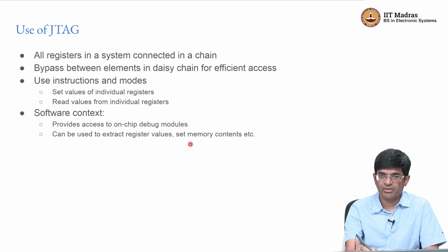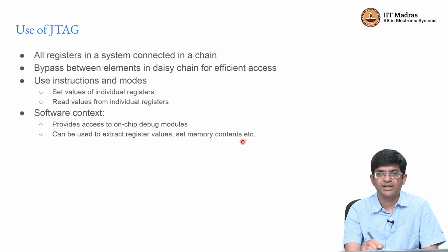And in addition to that, because of the fact that you can set individual registers, you can even use this in order to toggle certain bits and eventually slowly write values into memory. Okay. Yes, of course it is slow, but on the other hand it gives you an unbelievable level of control over what is actually happening in the hardware. So it becomes a very useful debugging tool.